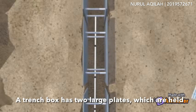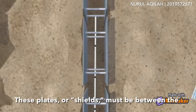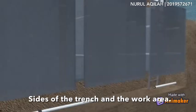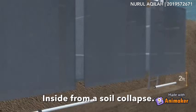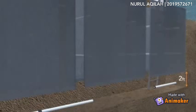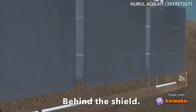The trench box has 2 large plates which are held apart by horizontal cross members. This plate or shield must be between the sides of the trench and the work area. The shields are strong enough to protect workers inside from a soil collapse. The shields can be 2 feet above the bottom of the trench as long as they can support the entire depth of the trench. There is no caving in under or behind the shield.